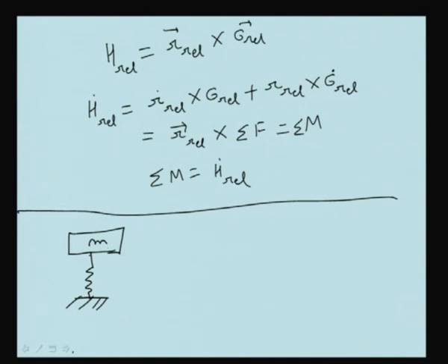In this case, the application of conservation of energy seems quite appropriate. If we drop a mass m from a height h above the unstressed position of the spring, then the spring gets compressed by delta. mg(h plus delta) is the change in the potential energy.